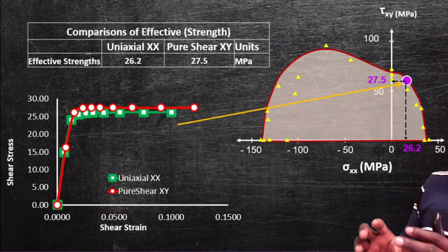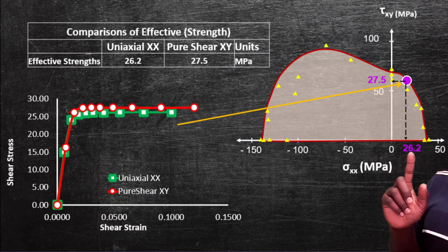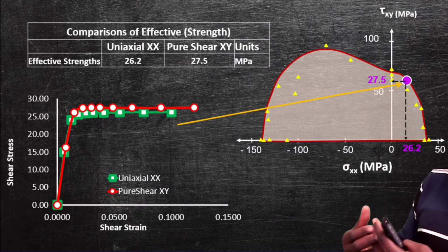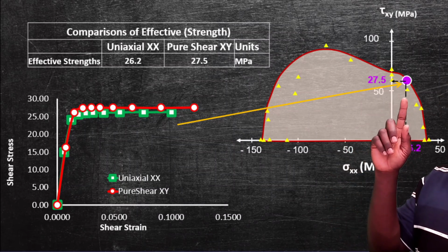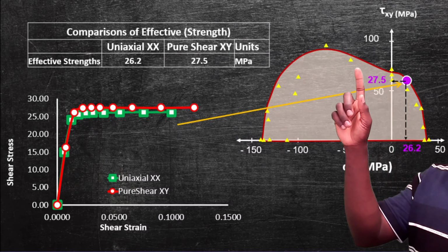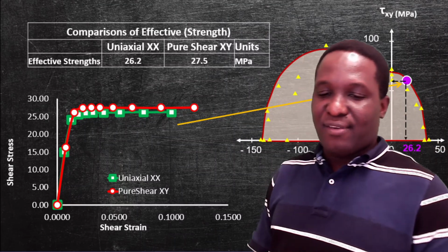So this is the value you get from an interaction of a certain value of uniaxial loading in the X direction with a shear which is loading in the Y direction. And this interaction will lead to a premature failure of just around 26, 27 megapascal. So you could imagine as you keep combining those two, you could keep going all the way around until you combine and generate all the failure points for this failure envelope. So this is how we're going to go about this. And hopefully at this point, we have given some insights to Ella as she tries to explore her problem of how can I generate a failure envelope for a composite material that the supervisor tasked her with.